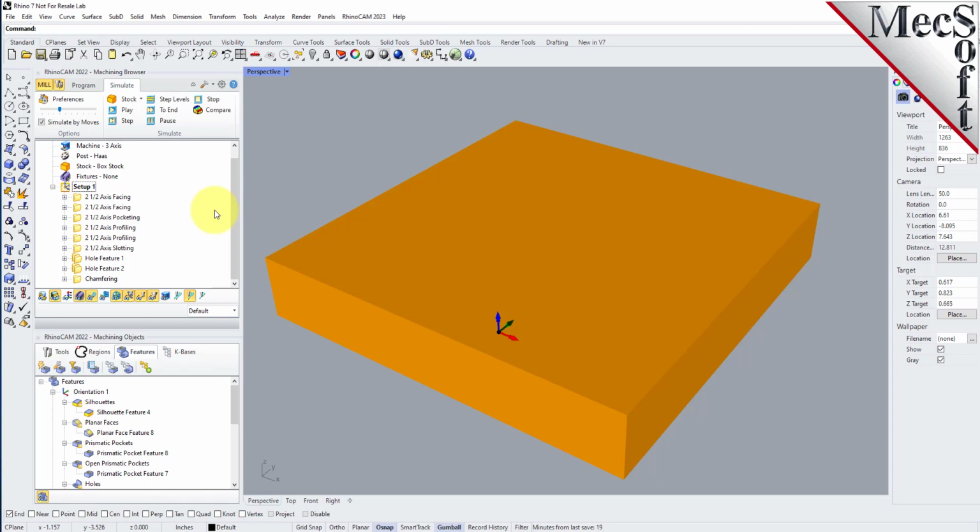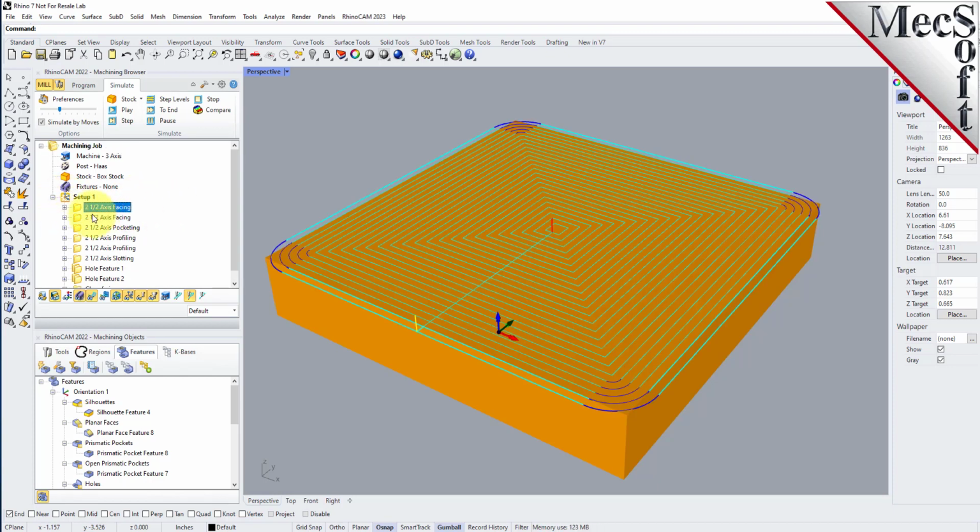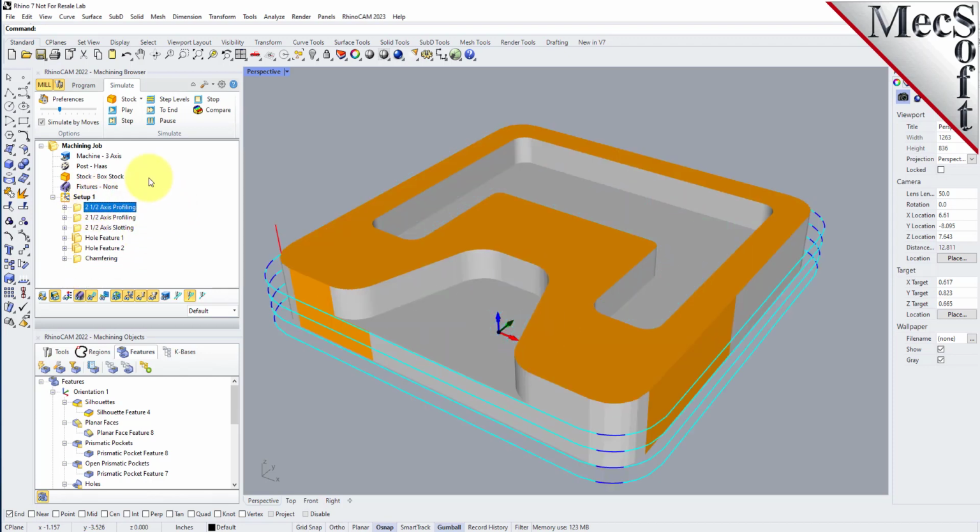Now one last thing I want to show you before I quit the video is you can also perform interactive feature machining. I know we're throwing a lot of acronyms out at you, but let's go over them real quickly here. We have automatic feature detection, interactive feature detection, and automatic feature machining. Now what if you want to just machine one particular feature? You don't want to do all of them, or you don't want to go through the process of doing all of them.